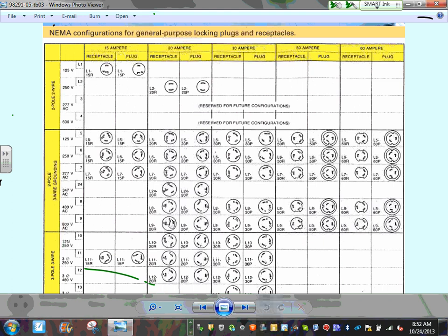So what would you do with something like this? Say a building ran out of power. They threw a generator outside, rent power. They come up with a cable like this. They plug it into a machine, and they cable it all the way to the building here, and they power you temporarily until you get your fixed power. If you have carnivals, you probably see a lot of 200 amp, 3-phase, 250 systems. That's how big these receptacles are.